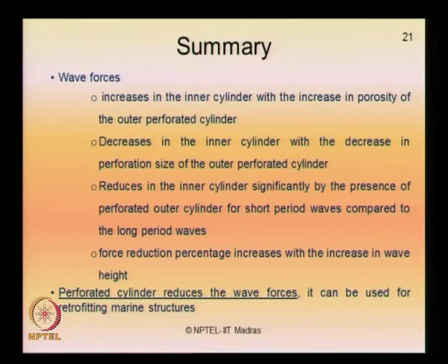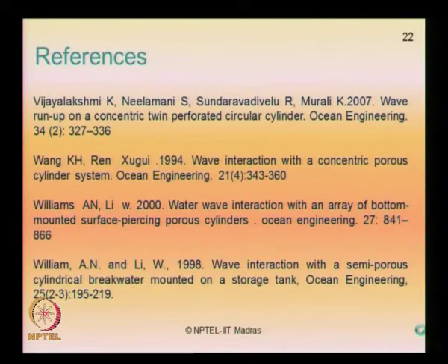So, we can see that the wave forces increase in the inner cylinder with increase in porosity, decrease in the inner cylinder with decrease in perforation size, and reduce in the inner cylinder significantly by the presence of perforated outer cylinder for short period waves compared to long period waves. Force percentage reduction increases with increase in wave height. So, perforated cylinder reduces wave forces, which can be seen as one of the direct methods of retrofitting marine structures. Subsequently, this has also been verified using numerical studies.